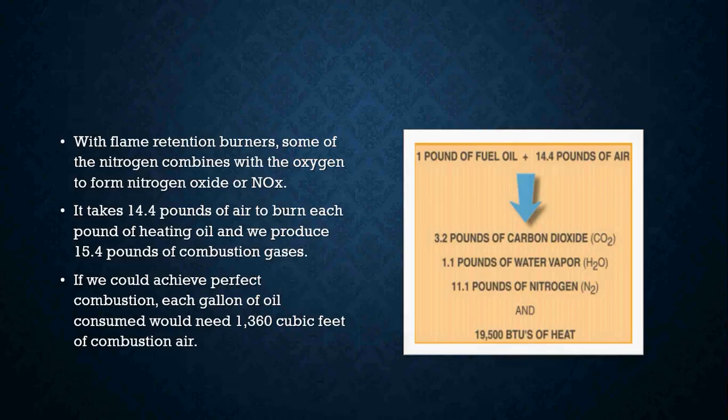When dealing with flame retention burners, some of the nitrogen combines with the oxygen to form nitrogen oxide, or NOx gases. It takes 14.4 pounds of air to burn each pound of heating oil, and we produce 15.4 pounds of combustion gases.